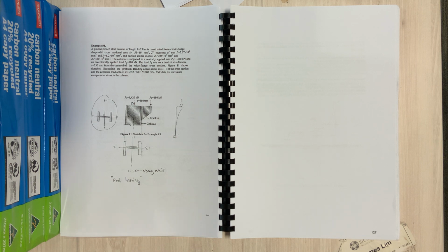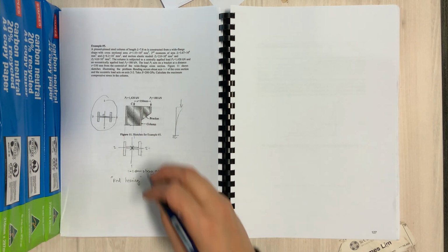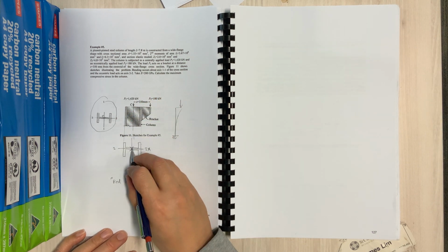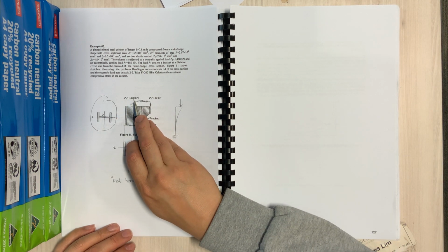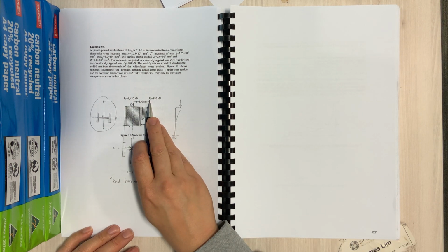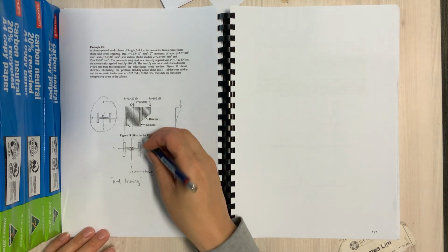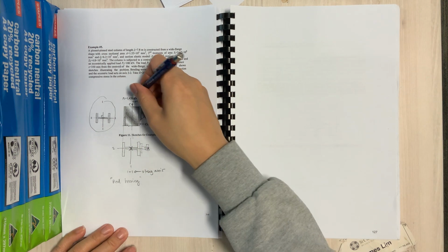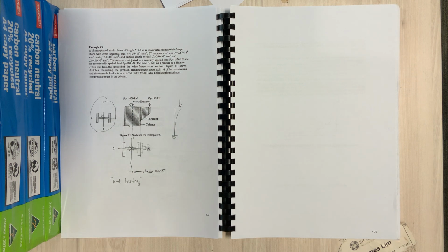So the column is subjected to a centrally applied load. So we've got one load, which would be applied at that point there, and then we've got another load which would be applied at that point there. So the centrally applied load right at the centroid of that section is going to be 1420 kilonewtons, and then the one that's here is going to be your 180 kilonewtons. That's going to be applied right at the end. So I'll put the bracket back into the sketch. But that's basically what's happening. You've got one load coming down here through the centroid, and then you've got another load coming down there.